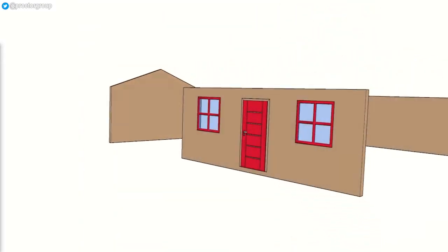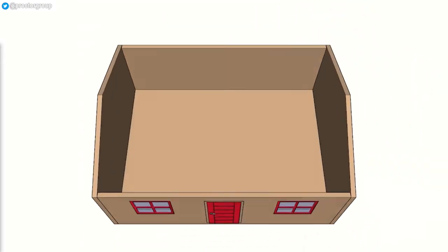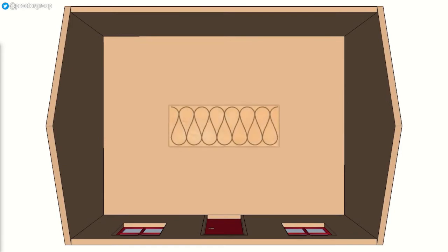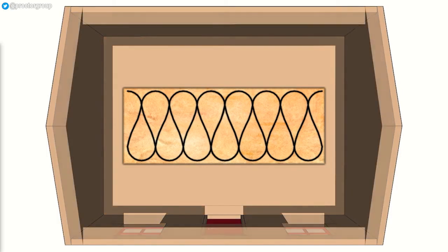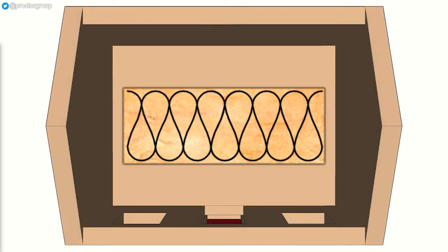This leads on to the second challenge in historical refurbishment, preserving interior space. While mineral fibre or natural wool do a good job ensuring moisture can permeate, their relatively high thermal conductivity means achieving modern thermal standards can require up to 200 mm of thickness, which is not always practical to incorporate into an existing space.